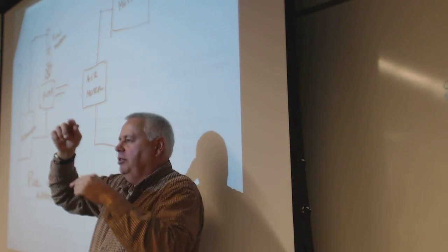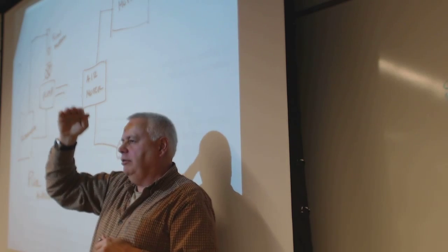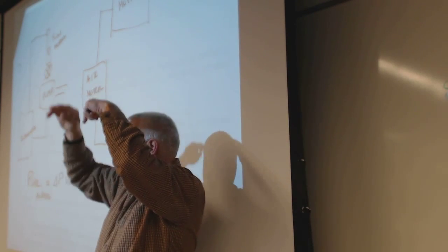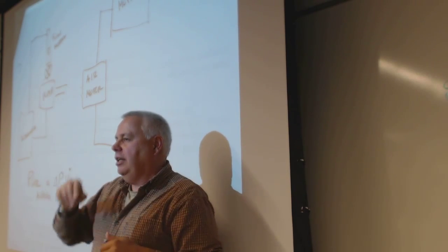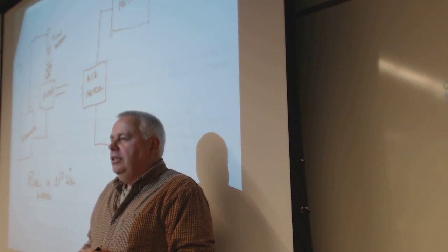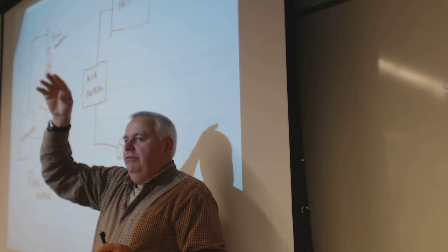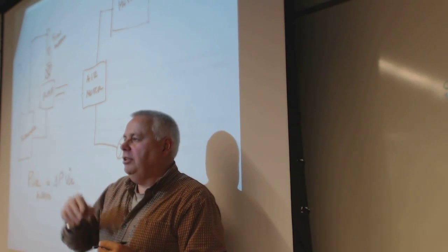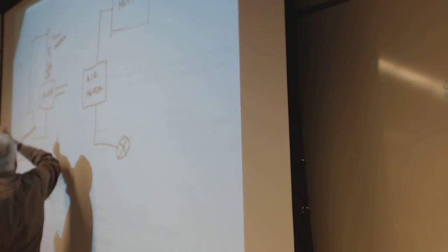It comes to a balance point, and you can balance it at one flow rate, it would balance here, and another flow rate, it balances up the gravity and the drag balance, and you can calibrate that, so there's a scale on it that scales how much it rises or falls, tells you the flow rate. So we have one of those for the water.